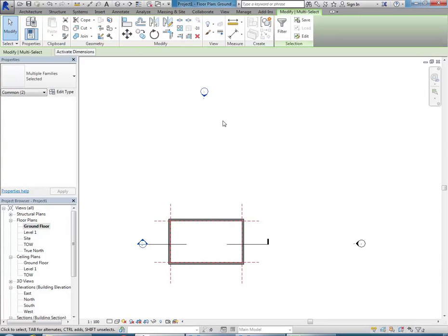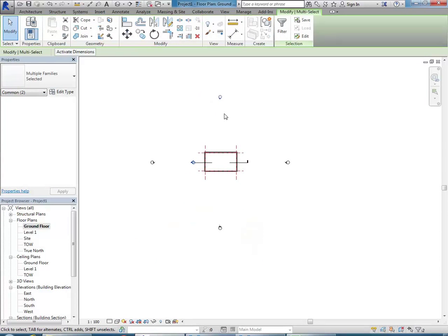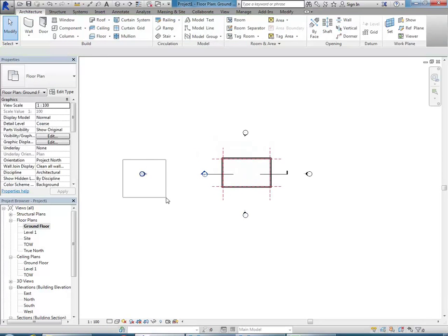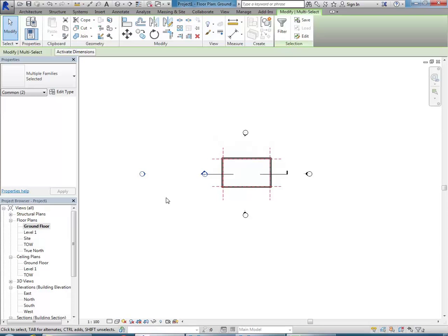If you make a window around it, and again, I'll use the arrows on the keyboard just to bring that in closer to the building, and do that with all four symbols. Just make sure you select with a window to get both of the objects that are there. If you just click and drag, it'll only get one, and that'll make things work differently.